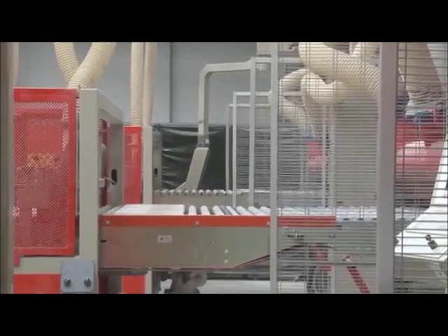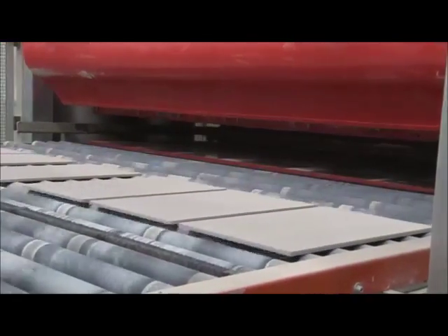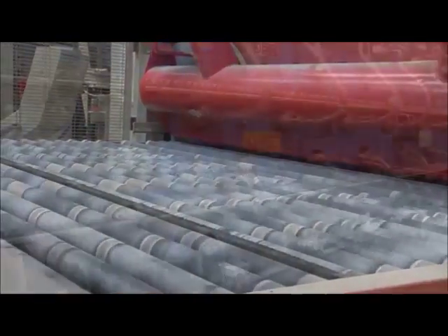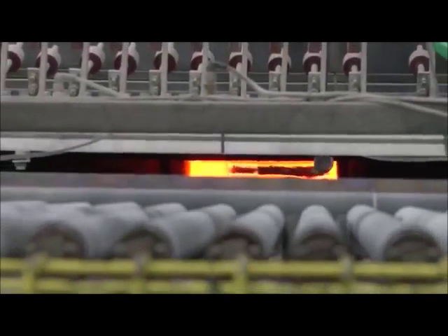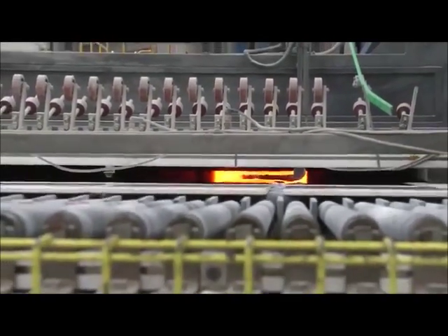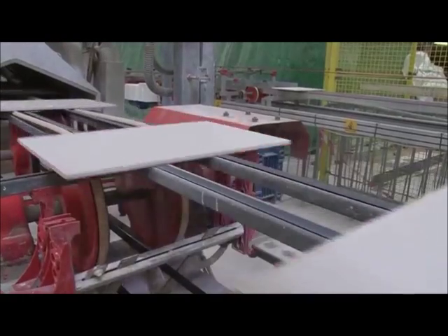A variety of pollutants are generated during the various manufacturing steps. These emissions must be controlled to meet air control standards. Among the pollutants produced in tile manufacture are fluorine and lead compounds, which are produced during firing and glazing. Lead compounds have been significantly reduced with the recent development of no lead or low lead glazes. The tile industry is also developing processes to recycle wastewater and sludge produced during milling, glazing, and spray drying.